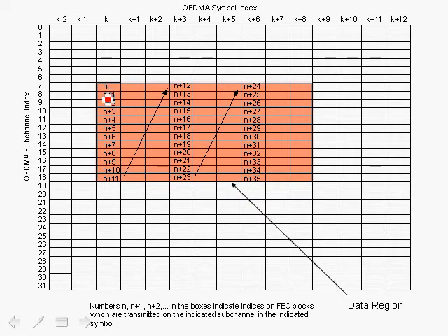Now as we get more data, then we go down in terms of subchannels and fill in the subchannels until we reach the boundary. Now the next OFDM time slot is 3 slots after, starting from the top subchannel within the region, and then as we get more data we move down again and then move across again 3 OFDM slots, and each 3 OFDM slots within a subchannel constitutes a FEC block.